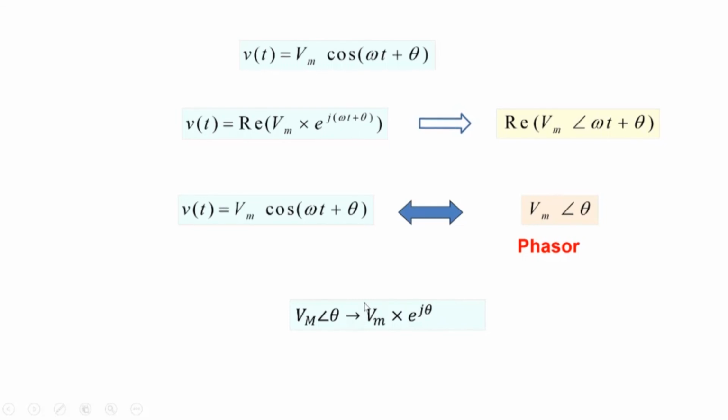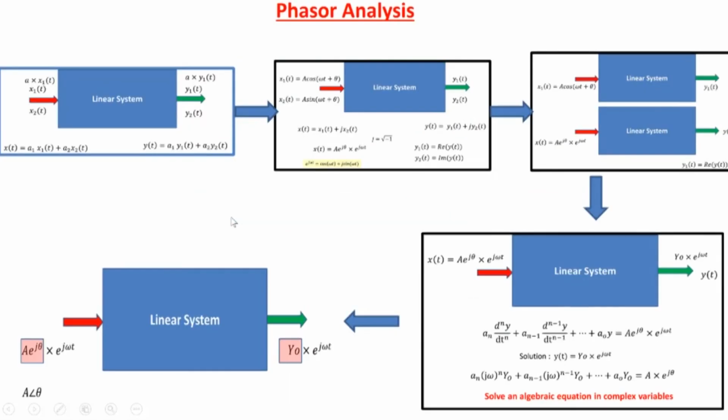So what we are saying is the analysis of a circuit to sinusoidal excitation is basically analyzing the signal in terms of phasors, where the input is cast in the form of phasors, and the output is then obtained in the form of a phasor. And anytime you can transform the phasor back to the time domain, the full signal that you're looking for. Okay, so this is the gist of our argument of phasor analysis.